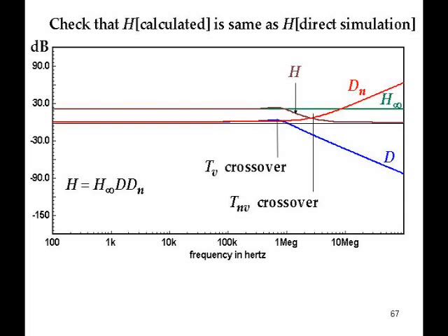Let me back up a minute on that one. Notice that the H does what you expect. It's equal to H infinity at low frequencies. It peaks up a little bit before falling off, meaning that the phase angle is not great. But it doesn't go to zero at infinite frequency. It levels off at just about 0 dB. If I drew this at a bigger scale, it would be just under 0 dB.